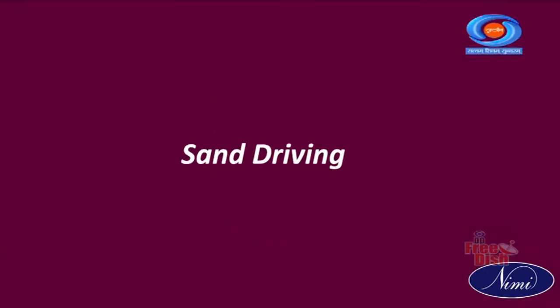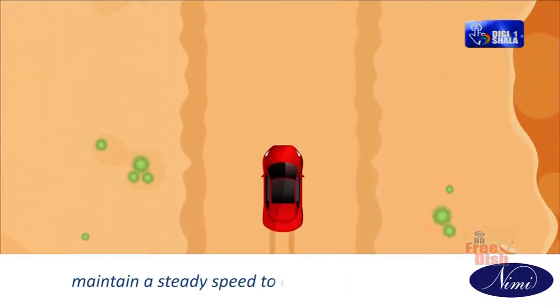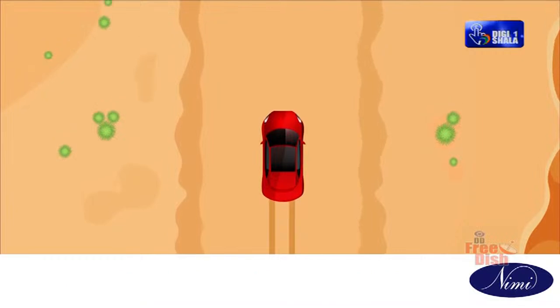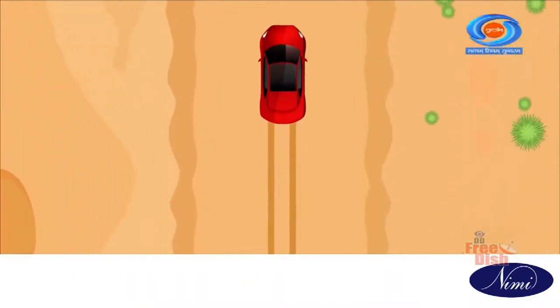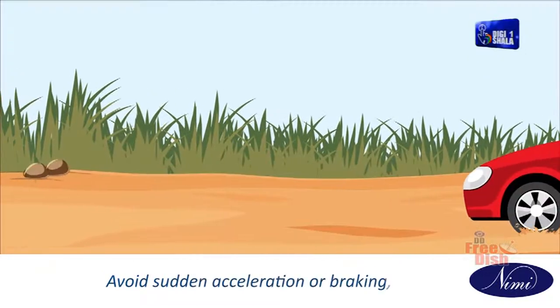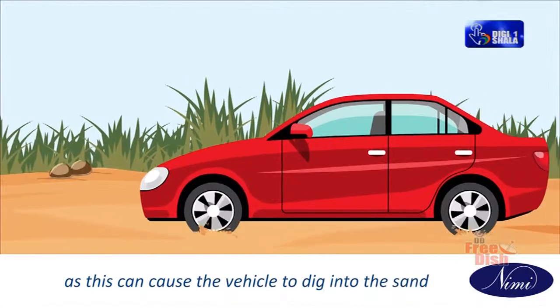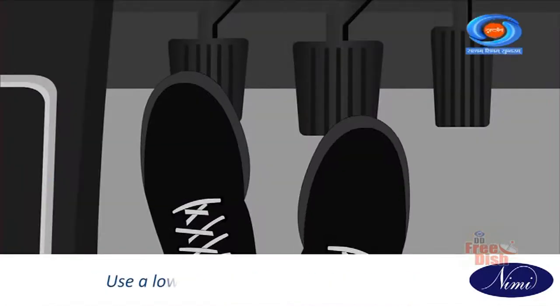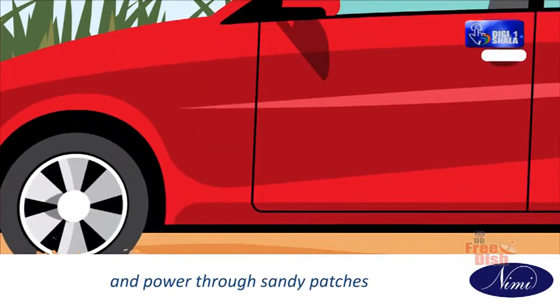Sand driving. When driving through sand, maintain a steady speed to avoid getting stuck. Reduce tire pressure slightly to increase traction. Avoid sudden acceleration or braking, as this can cause the vehicle to dig into the sand. Use a lower gear to maintain momentum and power through sandy patches.